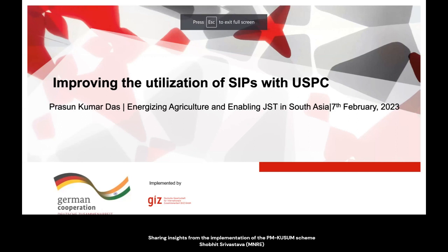So when we are solarizing through individual pumps, the costs are really high. One is that the plant size is very small, and as you go to higher sizes, you would definitely save money. The other thing is that under individual pump solarization, we were allowing additional PV capacity. Under feeder solarization, there's no provision of additional capacity, because the DISCOM is installing these plants and they have to meet the agriculture demand on that feeder.